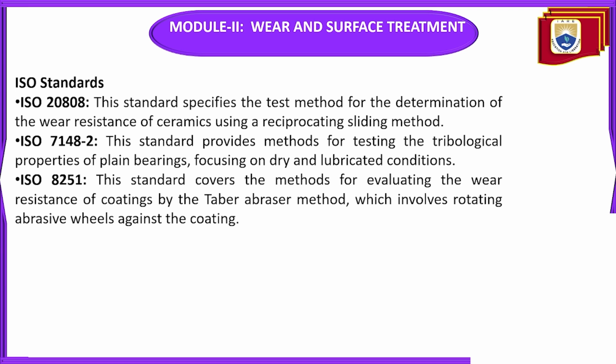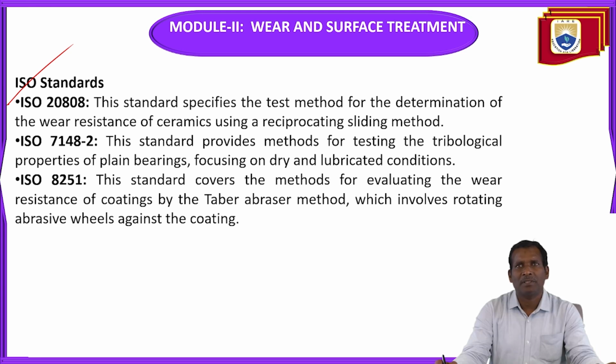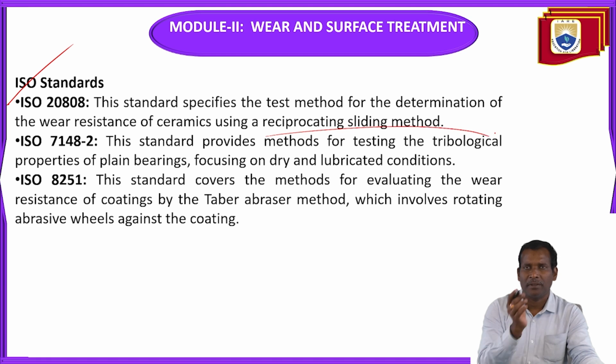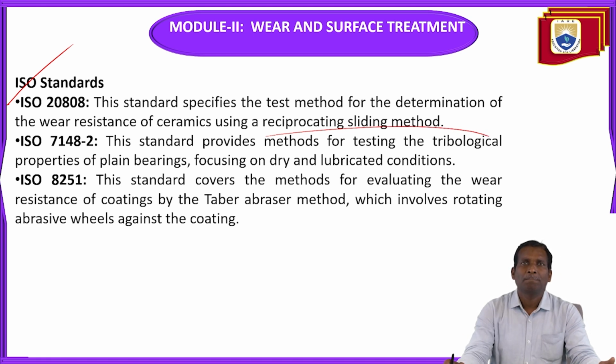Other standards are ISO standards. ISO 20808 specifies the test method for the determination of the wear resistance of ceramics using a reciprocating sliding method. So you can determine the wear resistance of ceramics using this reciprocating sliding method. The standard is ISO 20808.